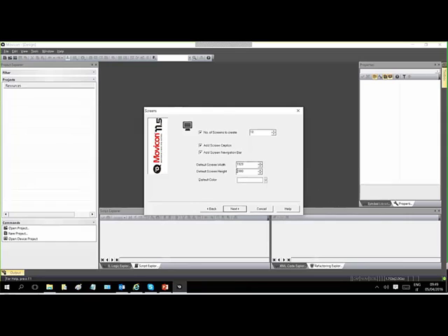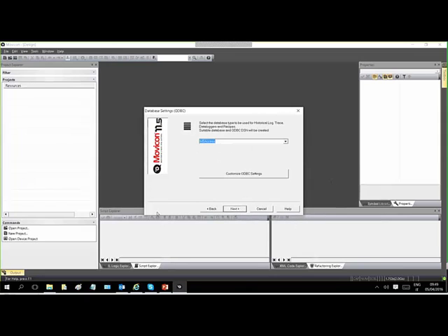If you want, you can insert this or remove it, up to you, and create it manually. About the resolution, Movicon detects the resolution of your monitor, and so creates the screen with this resolution. It's important to keep the end PC resolution for your synoptic. Background color, and continue.